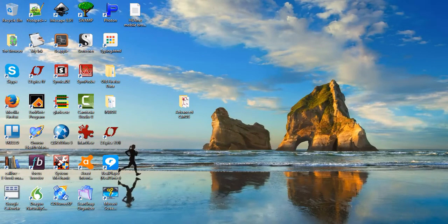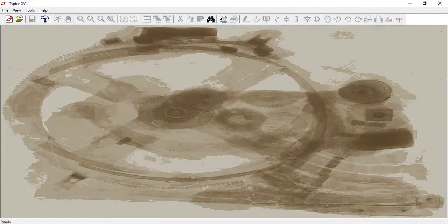Okay, we're going to take a look at the MOS transistor and examine its output conductance under various different scenarios. We're going to look at its behavior as VDS varies. We're going to look at its behavior as the temperature varies, as process varies, and finally we're going to look at device scaling, which is effectively the ability of the designer to change the transistor's W and L.